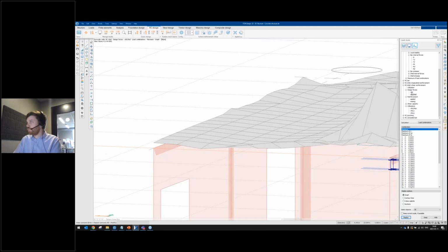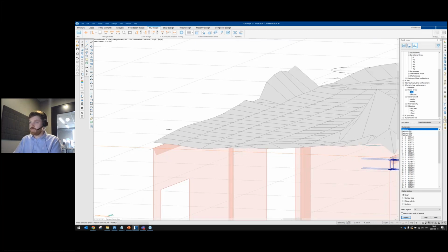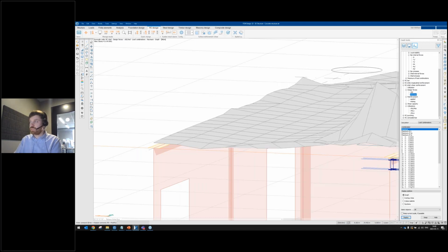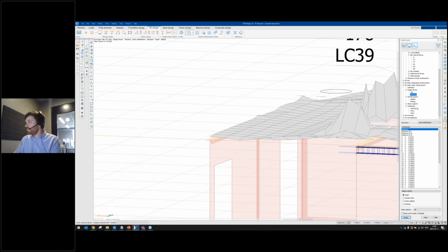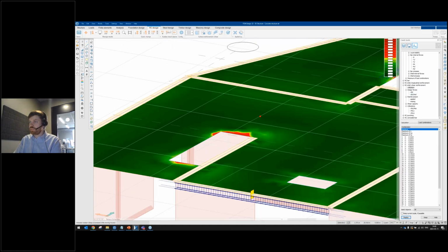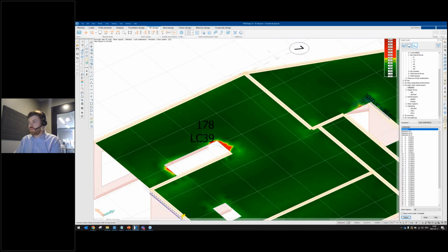So if I take a look at the normal shear force, it will be a little bit higher. That is due to the reduction in those shear regions that I defined using this tool, if you remember. So the force used for the shear design is the reduced one found under VRD reduced here. Let's take a look at the utilization again and apply some automatic shear links in this area.